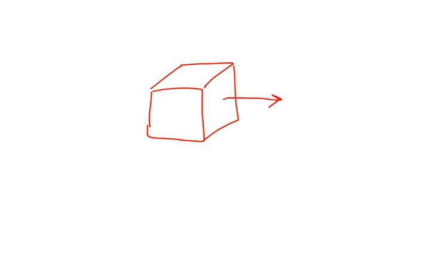Okay? So in a general state of stress, right, you could draw basically a cube to represent a point, and then we had said that on the cube, right, on every face, you had a normal stress, or a stress that's perpendicular to that surface, right? I'm drawing these so that they're all in tension, which would just mean these are all positive stresses, right?